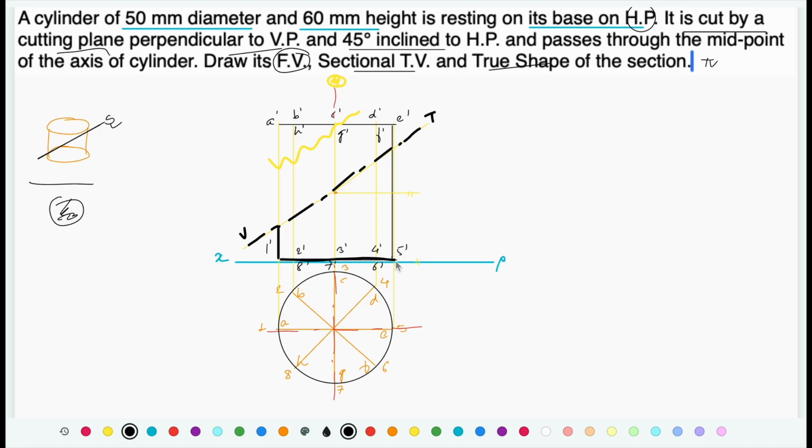This is the base, and till the cutting plane this line is also to be highlighted, and beyond that the top portion is going to be a regular line. Okay, so always highlight the remaining portion of the solid, or it should be differentiated from the part which is going to be discarded. So this is the cutting plane.